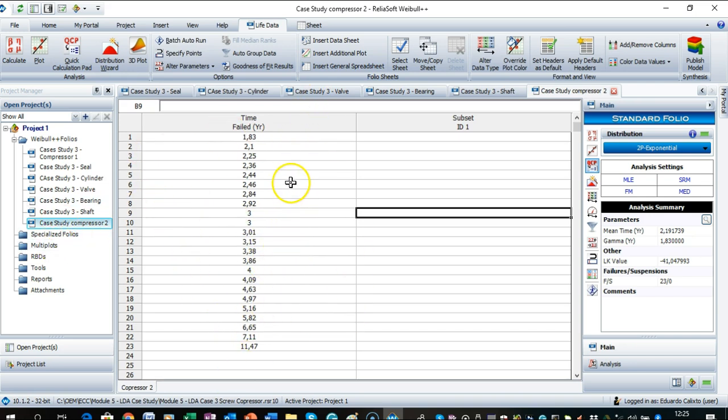So we need to understand that when we are preparing lifetime data analysis for a database or for a run analysis, we are not considering early life failures. We use that to avoid this problem in our system, but we do not expect that to happen again in a new project. So that needs to be very clear. Actually, for such equipment, seal, cylinder, valve, and bearing, we expect some increasing failures. That will actually happen if you look at such equipment later in the life cycle.